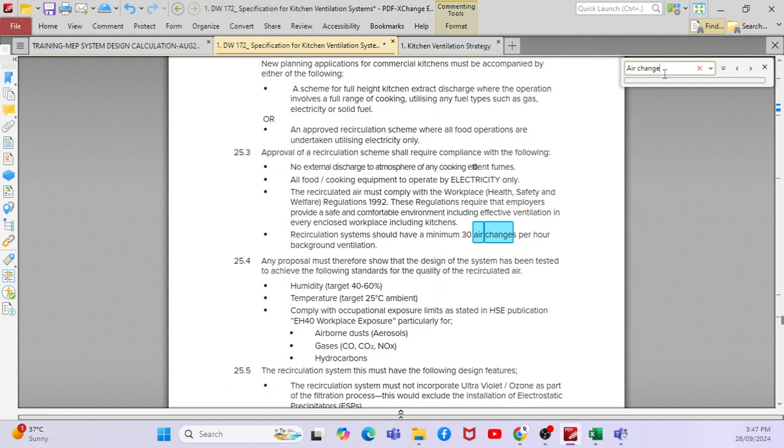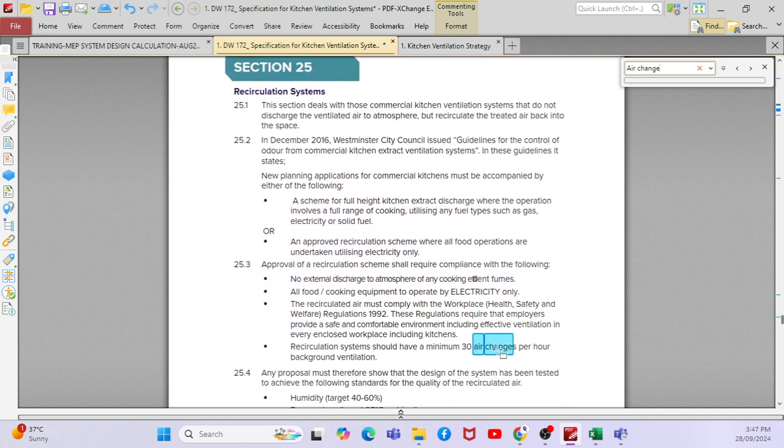Understood. But I think this factor still changes, right? Yeah, it still changes. See, when you want to do it for the concept stage, when you don't have any appliances in hand, you can calculate based on the air change per hour method. Understood, the ACH method. But that is only a rough estimation, for estimation purposes. But the actual ventilation requirement will depend upon the appliances, the type of cooking, and the size of the hood. So this parameter will change. Exactly. Understood.